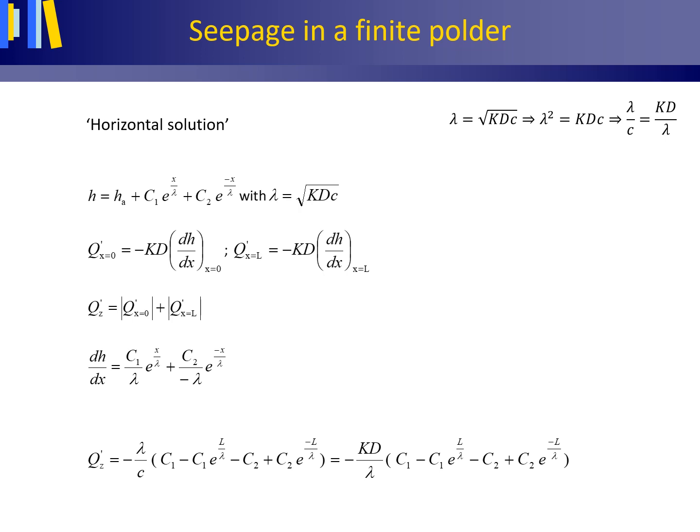If one wants to calculate the seepage volume flux into a polder in square meter per day, there are two routes one may take. In my book, there is a worked out example of determining the seepage volume flux for an infinite polder using both methods. Here I will discuss the steps to be taken for a finite polder. Please regard C1 and C2 as known values already obtained by having inserted the boundary conditions.